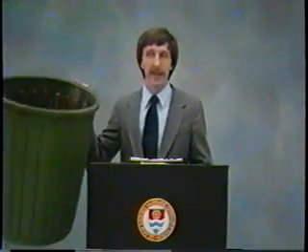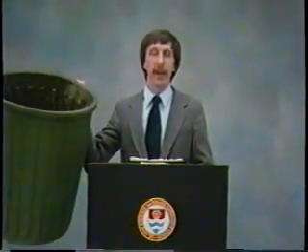In addition to measuring the pressure at the residual hydrant, we must also measure the discharge from the flowing hydrants. Since flow is volume of water per unit time, the most fundamental way to measure flow is to simply take a calibrated bucket and measure how long it takes to fill the bucket. Of course, those of you that have worked with fire hydrant flow tests know that a bucket like that would fill up very quickly and would be hard to hold while it was filling up. Therefore, we need some indirect way to measure the discharge from a fire hydrant.